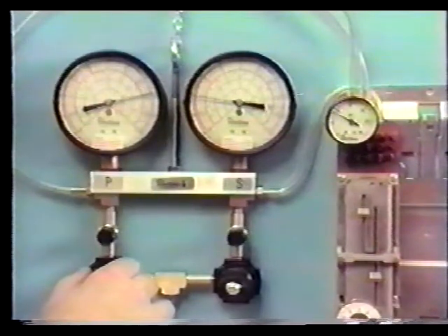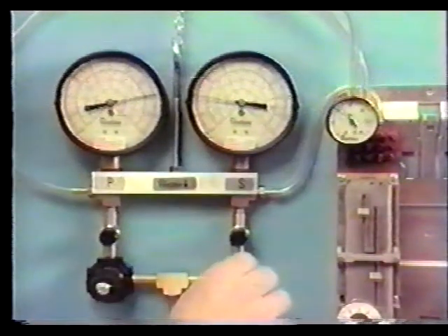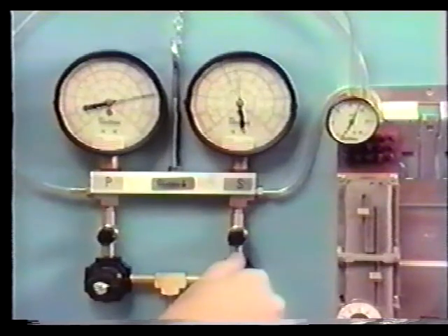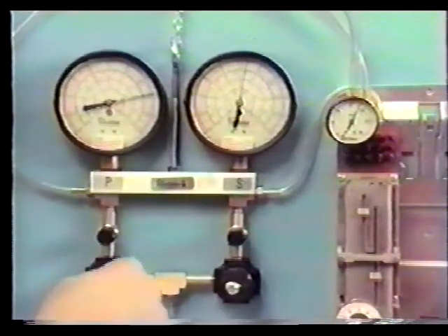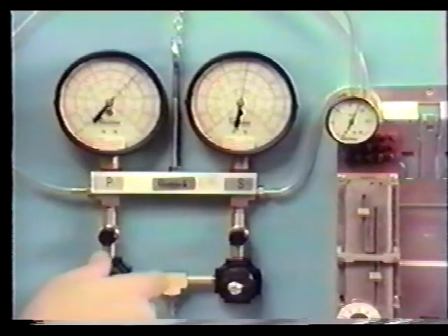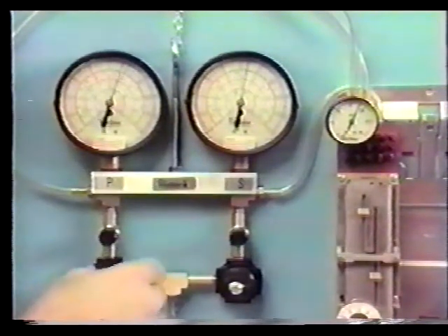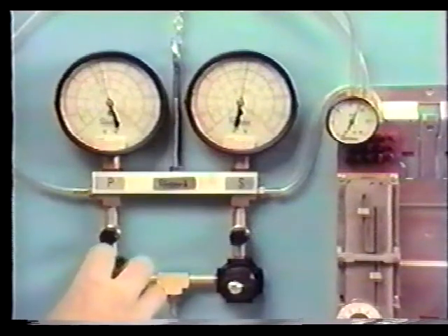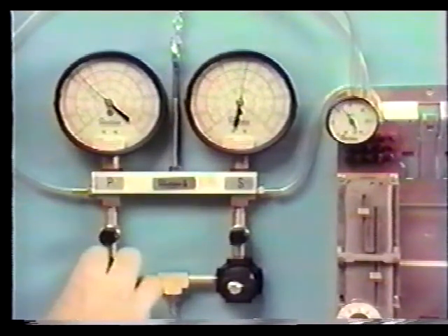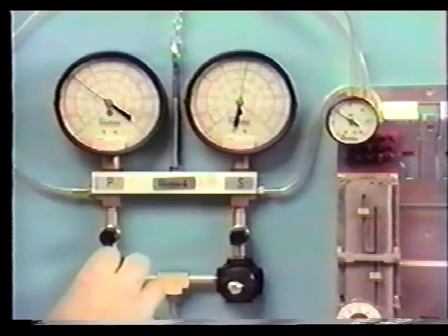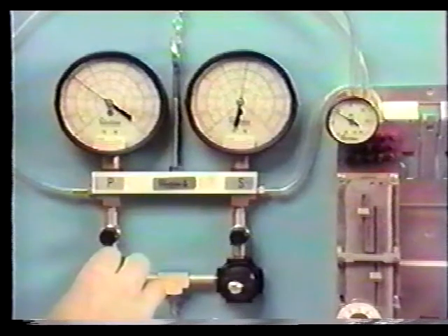Now, adjust the secondary input to the other end of the reset schedule, 55 degrees, and readjust the primary to get 9 psig on the branch line output. The primary gauge should read approximately 110 degrees. This concludes the bench calibration of the dual input receiver controller. It may be connected into a system with transmitters as long as they are of the same ranges as those used in the calibration procedure.